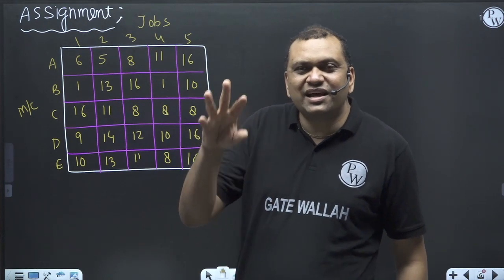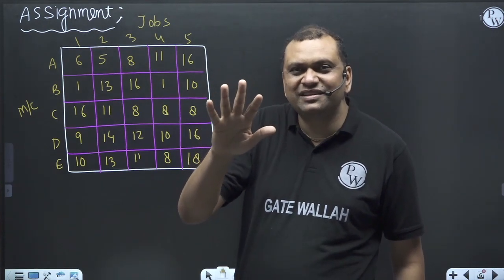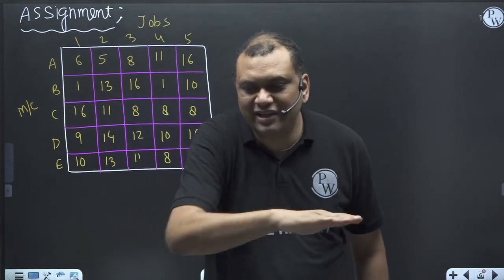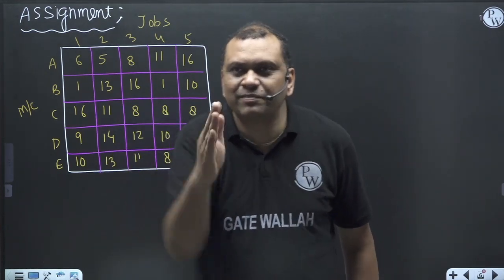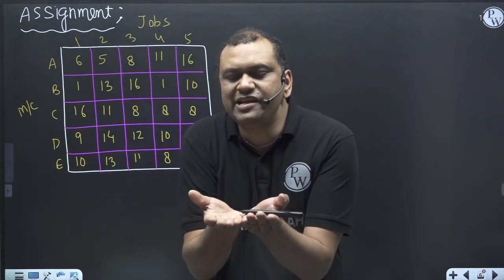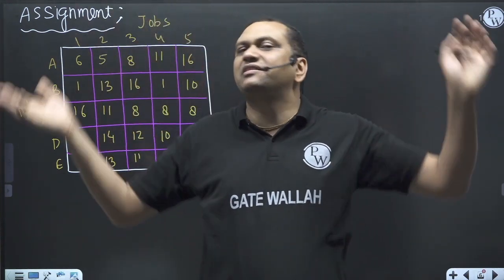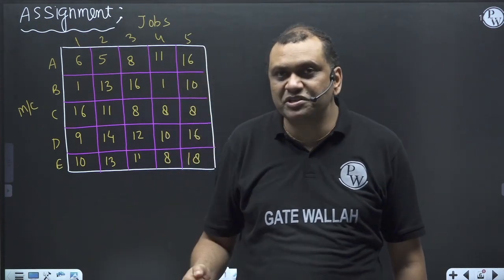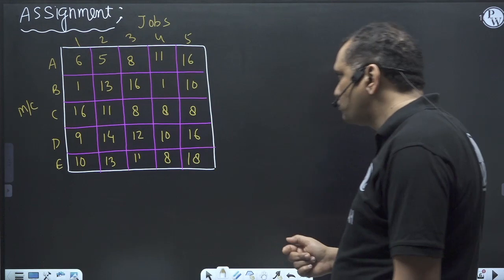Machining centers are at least 2.5 axis machines, meaning contouring can be done in 2 planes, this is one plane, this is another plane, and simultaneously linear interpolation can be given in the 3rd direction. It's a 2.5 axis. For details, see our automation lectures of the crash course.